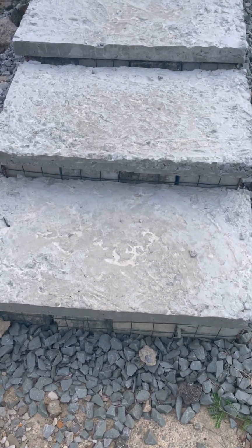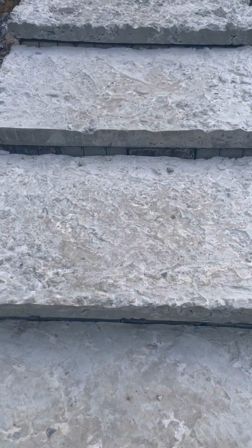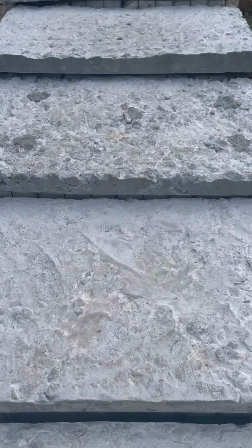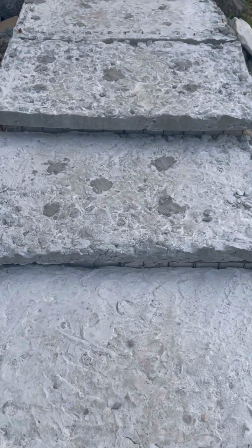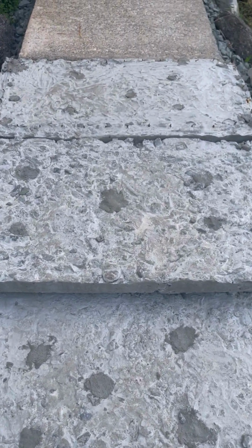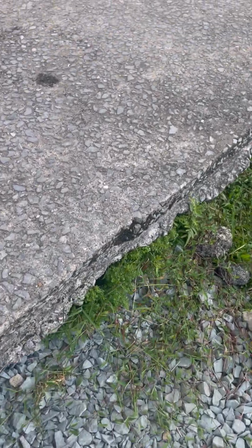In addition, this study also created a slope that is more stable, reducing the risk of landslide brought on by rain or other natural occurrence. Apart from being able to maintain the greenness of nature, these Gabion steps are also very quick to build and reduce the concrete cube waste in PKS.